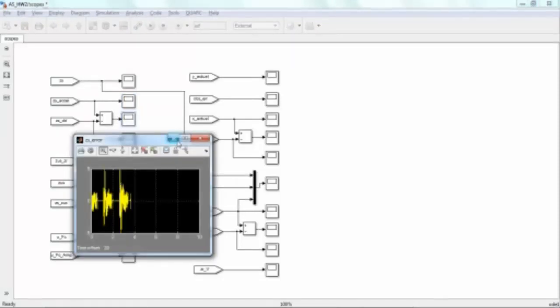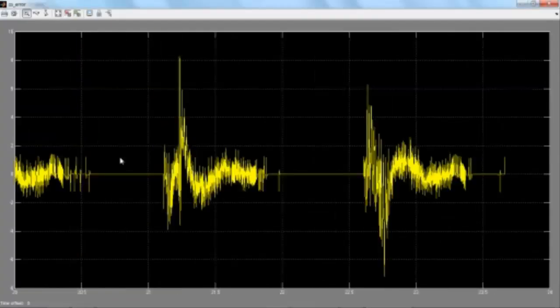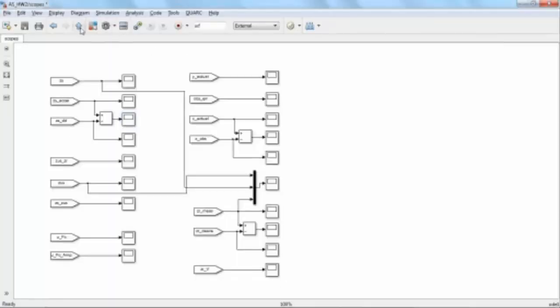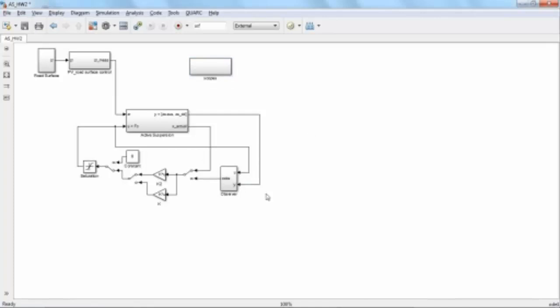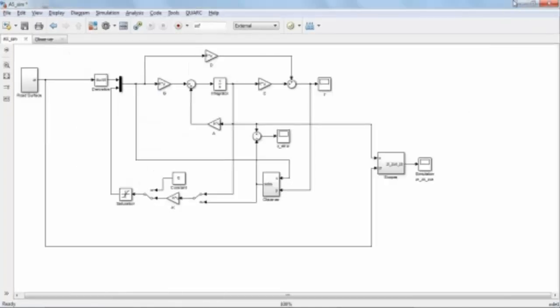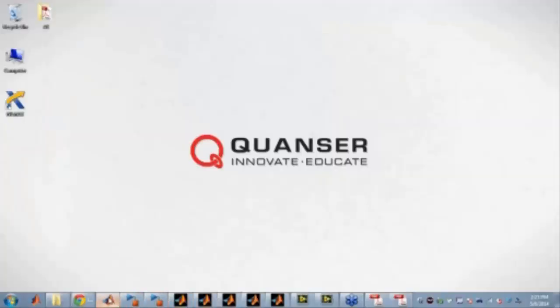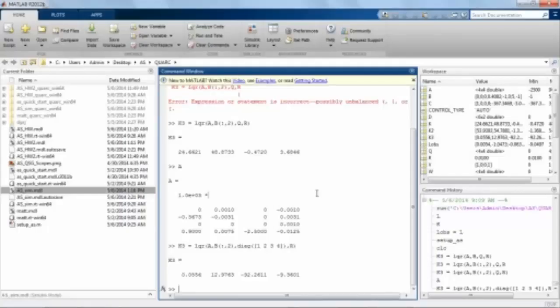Just to complete the discussion about this, I can show you the error between the two signals, and the error is quite significant at times. As we would expect, since we are using derivative filters, we have quite some noise in the background. So the mean is fairly close to zero, but we have a large variance in our system. So the obvious thing to do is to design a proper observer. Now, the idea of the observer is that we get something that can only use the output information that we can directly measure, and then tries to estimate all our unknown system states with this information.